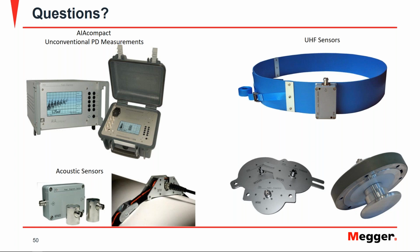Accordingly, you have a different attenuation profile for each type of GIS. It depends on the voltage level, but there are also differences between different manufacturers. And then you have to take into consideration that different types of sensors have a different sensitivity. Some of them are better than others. So it depends on so many factors that you can't give a precise answer to that question.